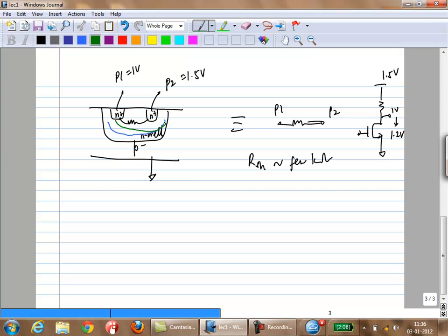What does this mean? Obviously you are depending on the movement of charge carriers through the N-well to get your resistance. If this voltage changes, the depletion region changes, which means the resistance of your N-well between those two nodes is going to change, right? So in reality, your current to voltage, this is your ideal situation, but it could very much look like some kind of nonlinear relationship. So in cases where linearity is very important, and in cases like this it probably is quite important, you don't want to use an N-well resistor in most cases.